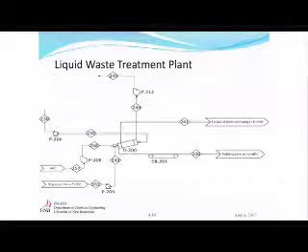As for the fuel for the indirect fire rotary dryer, we're using glycerol, which is a co-product from the biodiesel production process. And as there is no market for this glycerol right now, we're using it as a fuel in the indirect fire rotary dryer to cut down the utility costs for the plant. The flue gas from the combustion process of the glycerol will be sent to the NOx process.